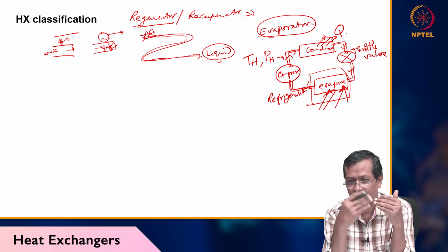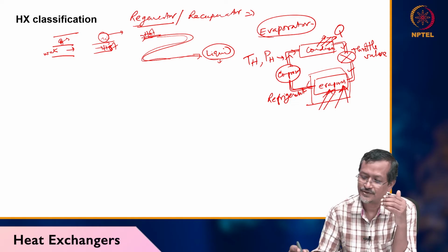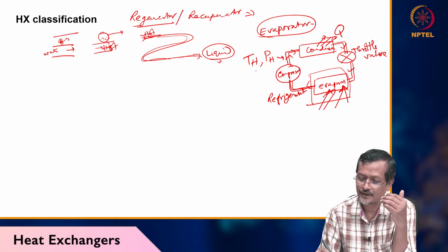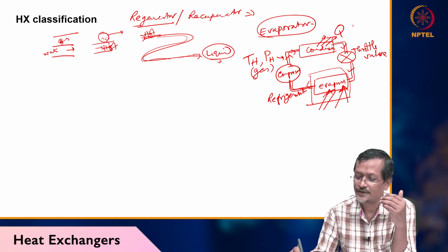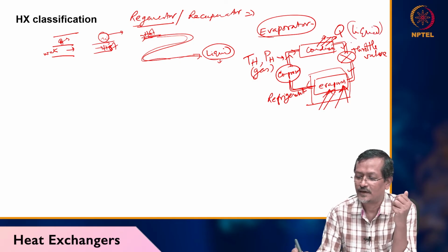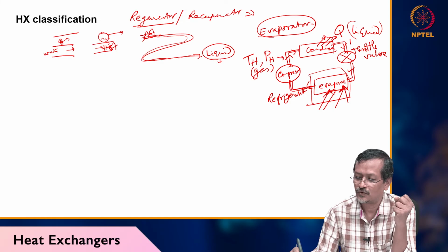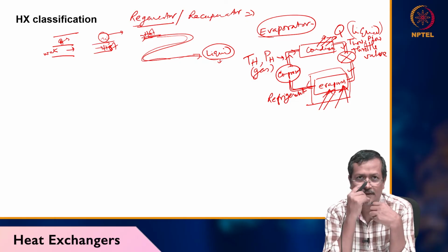When it is released, lots of heat, so that high temperature, high pressure gas. Okay, now it will be liquid. Okay, temperature will be low, low temperature, pressure also low. Okay, low temperature, low pressure created after condenser.